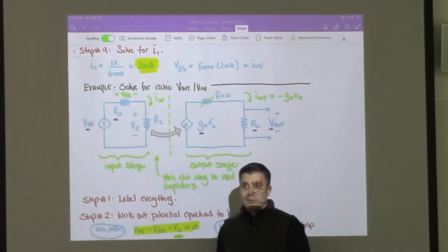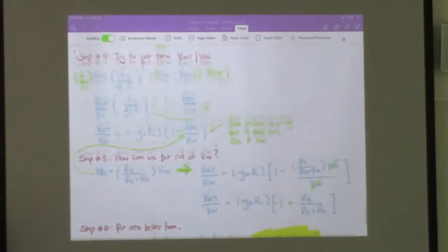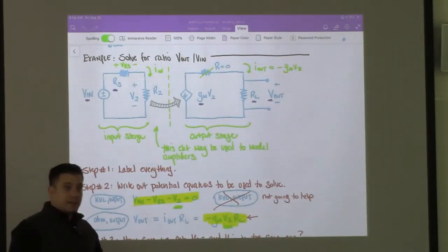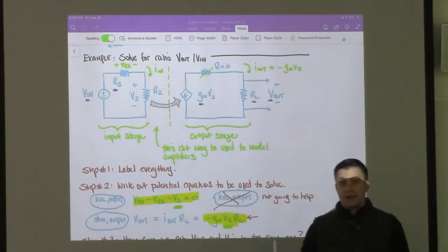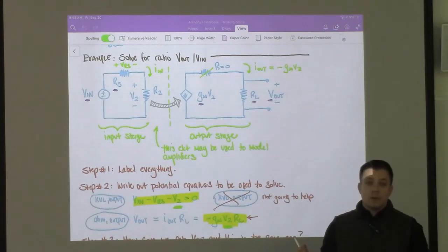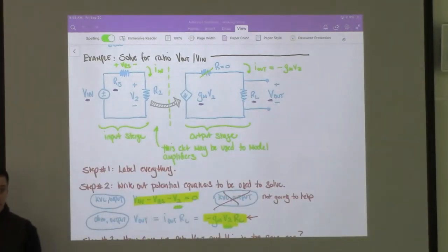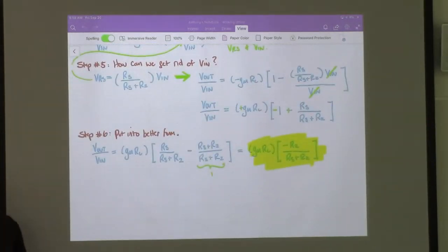That sounds familiar? And so the nice thing about that expression is it has a V in in it. We already have a V in in our equation, so at least it's not adding another unknown. It may be adding another instance of an unknown we already have, but it's not like using Ohm's law where we stick an I1 in there and it's almost like we're digging the hole deeper. And if we get lucky, maybe they'll cancel out. So that's the substitution we make here.